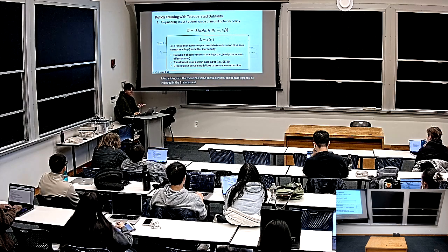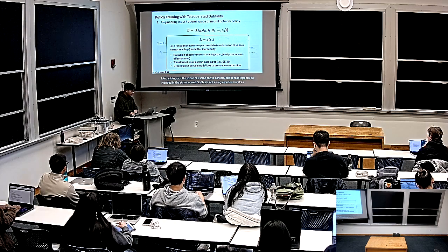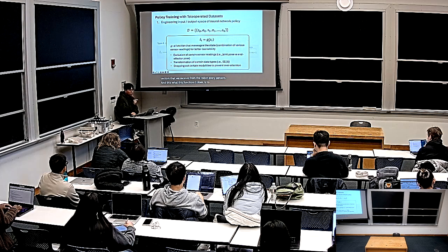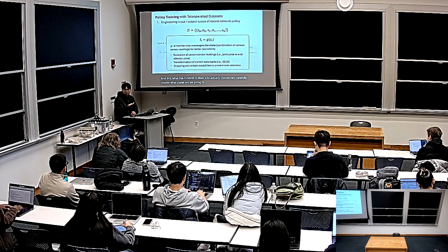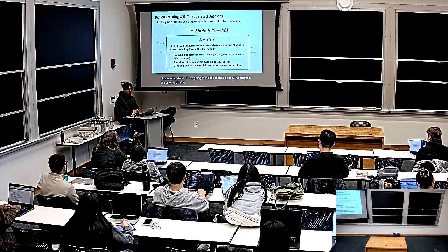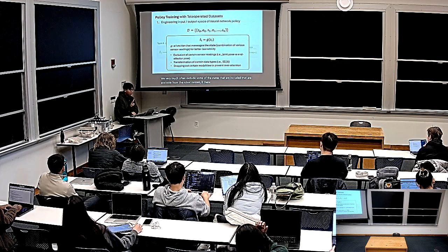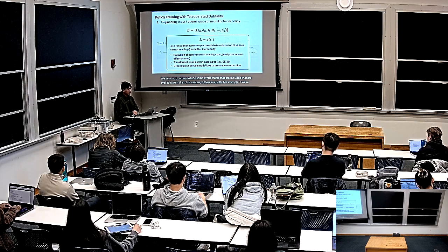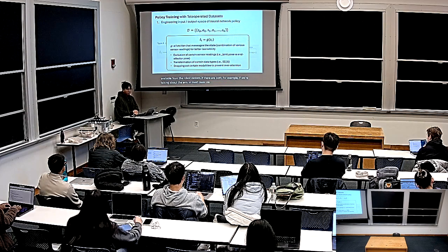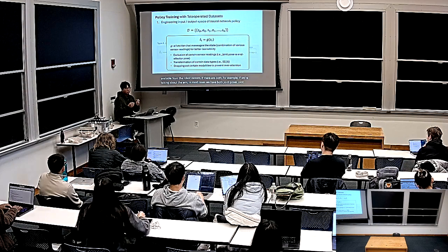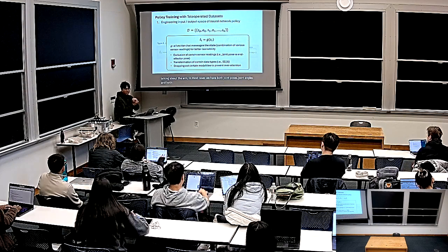So this is not a single vector, but a set of vectors that we receive from the robot's sensors. What this function G does is to very carefully choose what states we are going to include to train a policy. For example, we very often exclude some of the states that are available from the robot's sensors. If we're talking about the arm, in most cases we have both joint angles and the end effector pose in SE3 space.